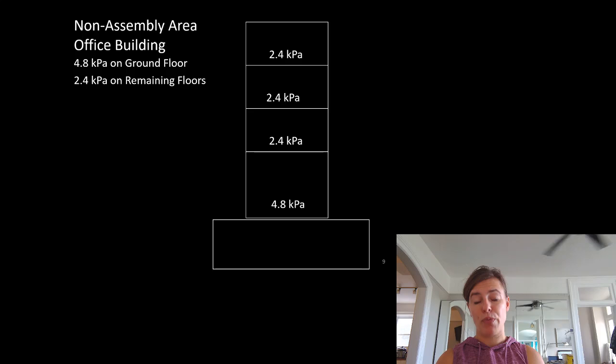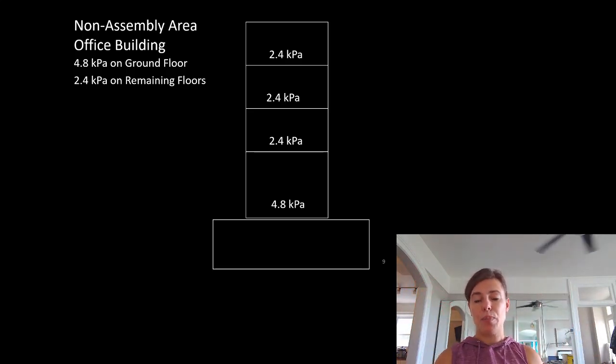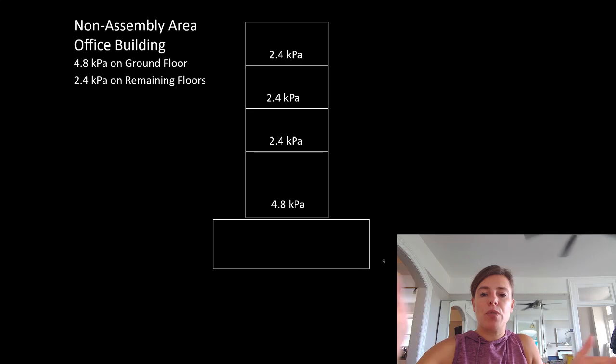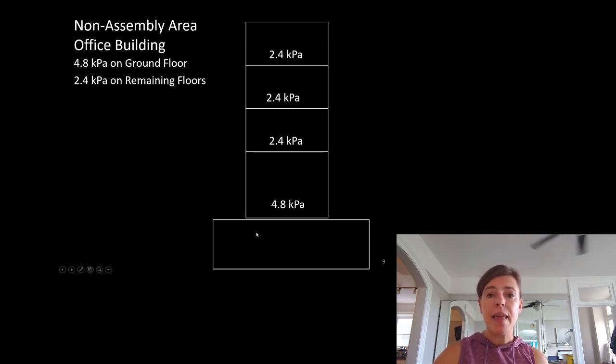A lot of the setbacks for properties are about the above spaces, so how much space there is around the building above grade. Often, and you have to be double certain and check this with your building department, you can build right to the property lines below grade. So that means that this space right here has a big impact on how we design this floor.